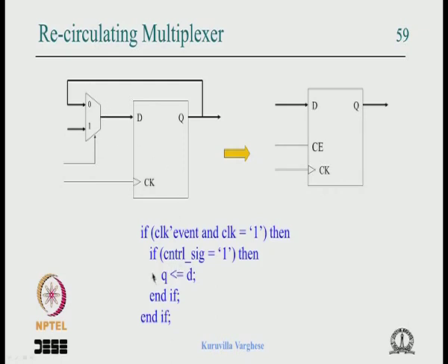But definitely, if you have an else control signal, then another mux has to come outside, which will be implemented in the lookup table rather than in the flip flop. So normally, on average, you will have mostly one control, and that is built into the FPGA. It's quite good because otherwise the lookup table would unnecessarily get used for a 2-to-1 mux, and by building that into the flip flop the lookup table is saved.